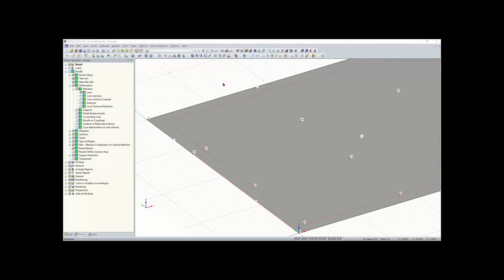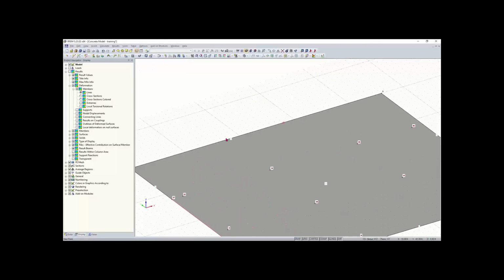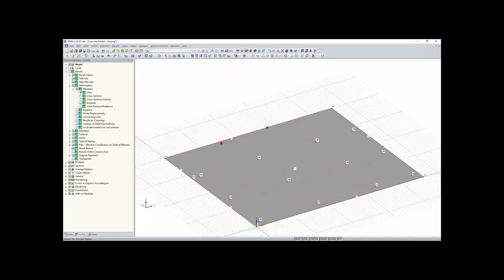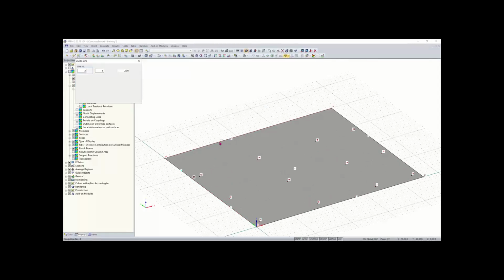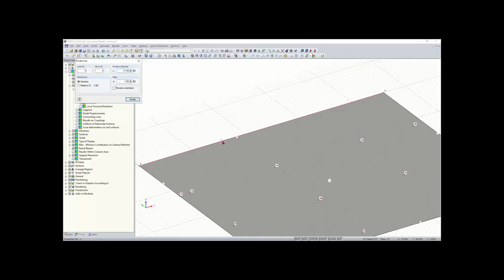and now we can do the same thing for this line up here at the top. I'm going to click on it. I'm going to right click, select divide line graphically. And maybe just to reiterate what graphically means is you can see I can just snap or place the node wherever I want to on the line graphically using my cursor.